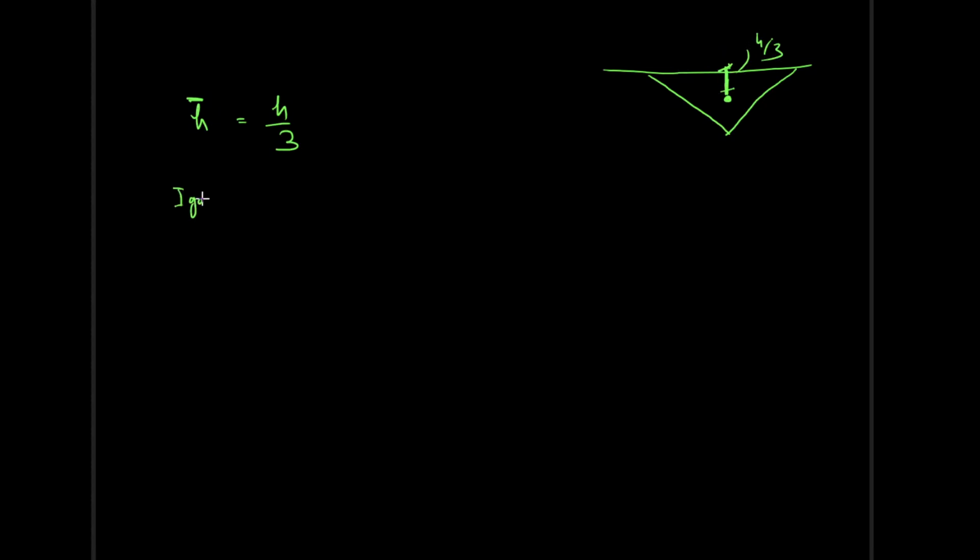And what is the moment of inertia for a triangle? It is b into h cube upon 36. So this is the moment of inertia. Now let us calculate the HCP. That will be h bar plus IG by the area into h bar, times sine square 90 degree.